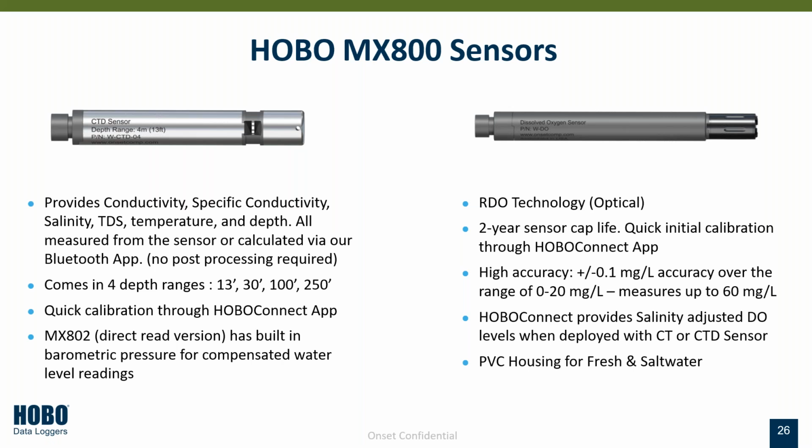So when it comes to maintenance and cleaning these off, that's really site dependent, right? If you're in an estuary in the summer months, you're going to have to go out there pretty frequently. And when I say frequently, a week or two, you might have to go out there and clean these sensors off. And that's the case with anything. But in colder times, fast flowing water, a stream, not much fouling, you can get away with months at a time leaving these out there. And it's the same thing with the CTD sensor.